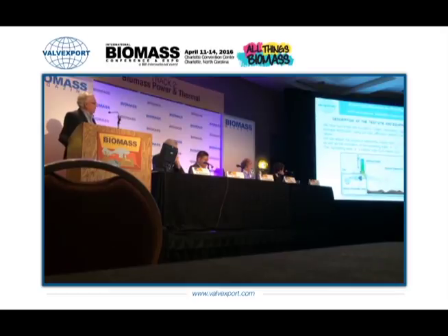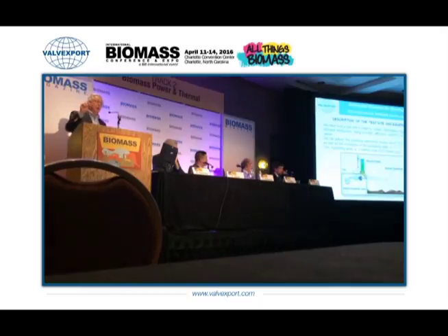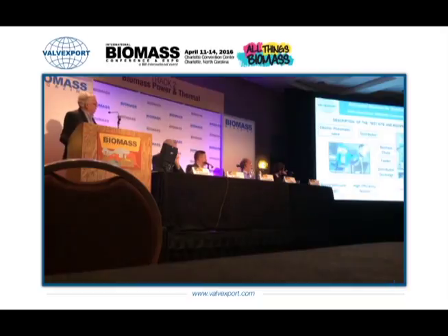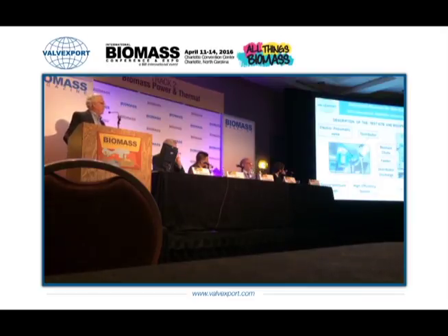We can adjust the pressure between 1 inch and 25 inches in steps as close to half an inch between steps. So if you connect this to a DCS, you have total and complete control of where at each second you are throwing the biomass onto a grate. So this is an electropneumatic valve that we are proposing as the means to achieve this. It's run through the DCS control and the already prepared programs for that biomass and that grate.